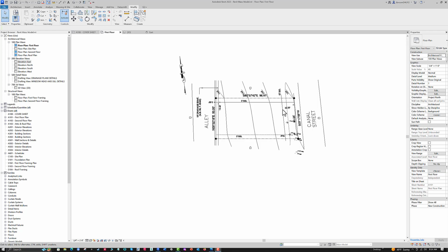And this is 15 feet from the property line, not 50 feet from the curb. The reason for these setbacks is to provide some fire space between the building on this lot and the building over here, and also not to create too crowded a look in the neighborhood streetscape.